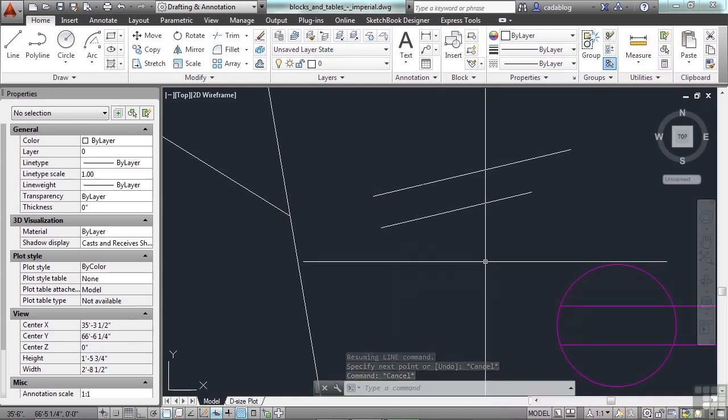I want to talk about what's called Object Snap Tracking. I like Object Snap Tracking. With this, the cursor can track along alignment paths of different objects, based off of other object snap points. And then when specific points are set up, then you can use them right in the command. A lot like that apparent intersection that you saw.